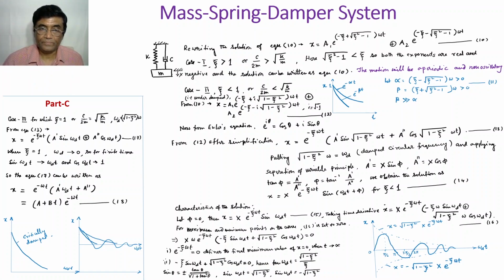It signifies that in the overdamped situation, depending on alpha and beta values, which depend on zeta, the exponent attached to the beta value will decay faster than this, isn't it? Just check it. It's very common sense. So there will be no oscillation, the motion will be non-oscillatory, no periodic motion.